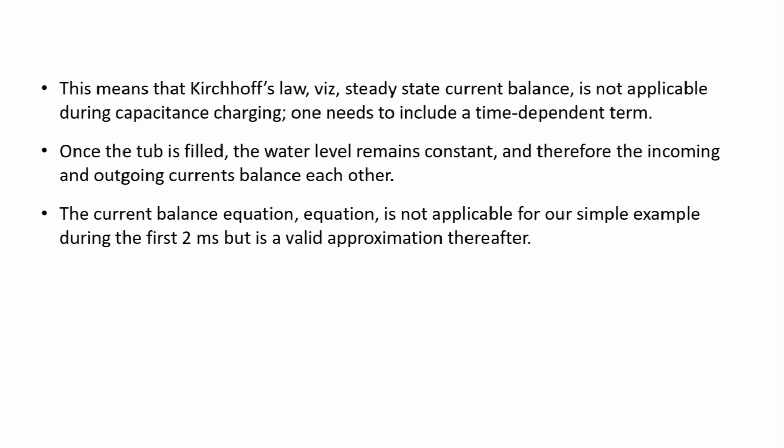So, the current balance equation is not applicable for our example during the first 2 milliseconds. We have found earlier that the charging time takes 2 milliseconds. So, within 2 milliseconds, when it is charging, you cannot apply the current balance equation, but you can apply it thereafter, when the balance is obtained, which is when the ingoing and the outgoing currents balance each other. Then I can apply the current balance theory.